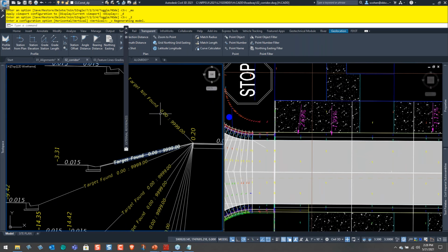Okay, so by adding them as target founds, what that says is this: these will never be found unless you actually target them. So for this scenario to work, what I would have to do, in fact, I believe it's this one right here. So this is, if I hover, and the key thing, name them. I cannot stress that enough. Name all of these. And the little trick that I do with corridor modeling is I actually name them in the order that you see it.